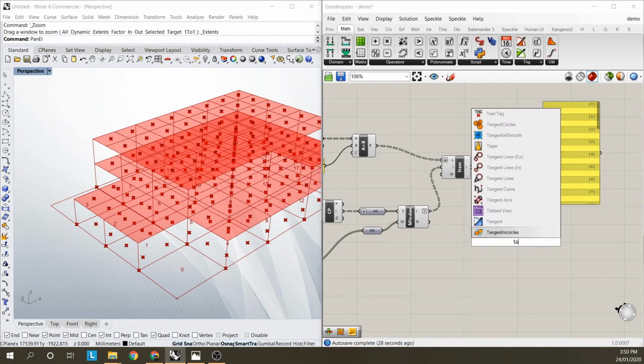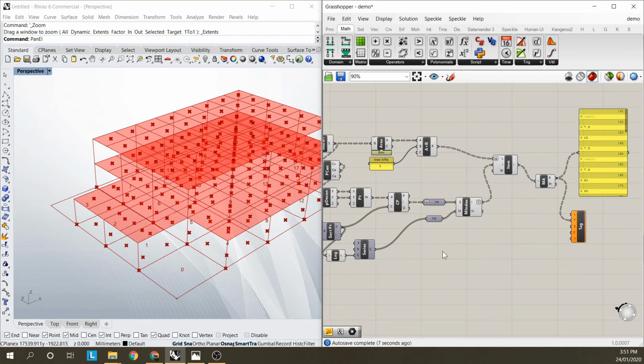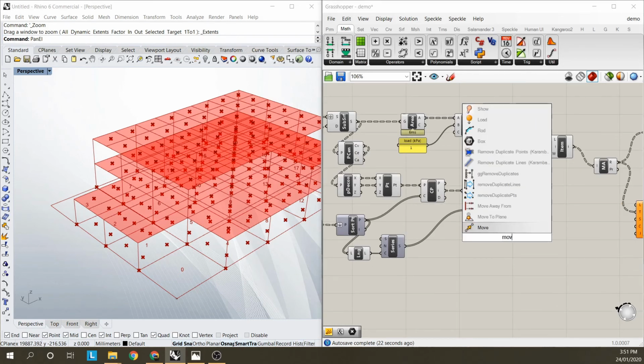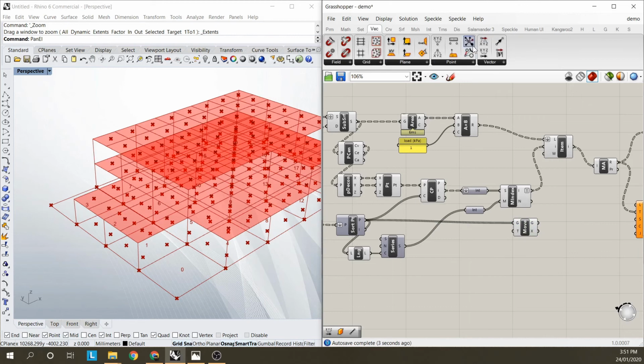So I'm going to use tag, except I want to use a bit better tag than the simple one, so I'm going to use this 3D tag. I know the text that I want in the tag. The location, I'm going to get that from previous information, which was the original points, the list of 30 points that I had. But I just want to offset it a little bit because I don't want it stuck right under the column. So I'll just get a vector here.